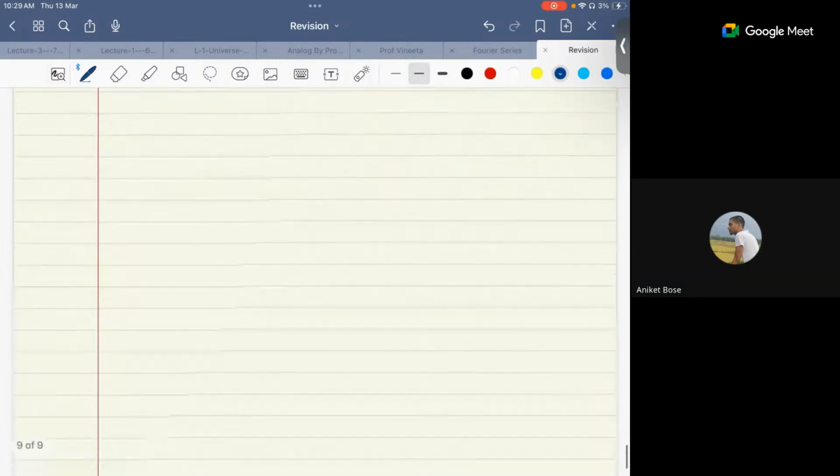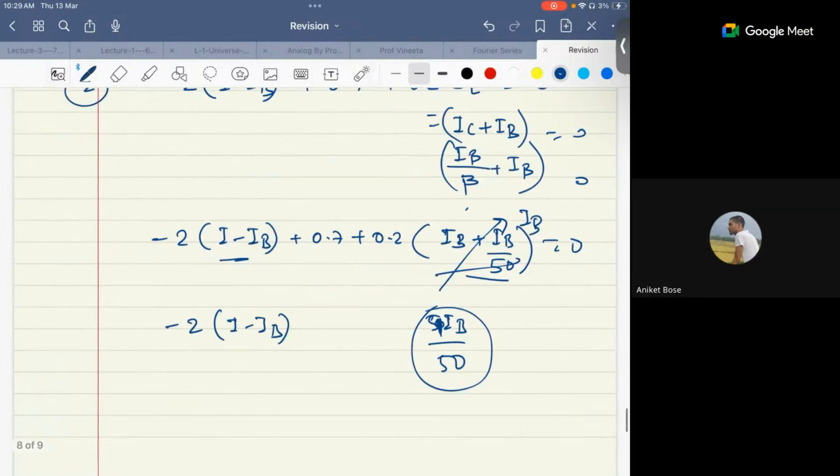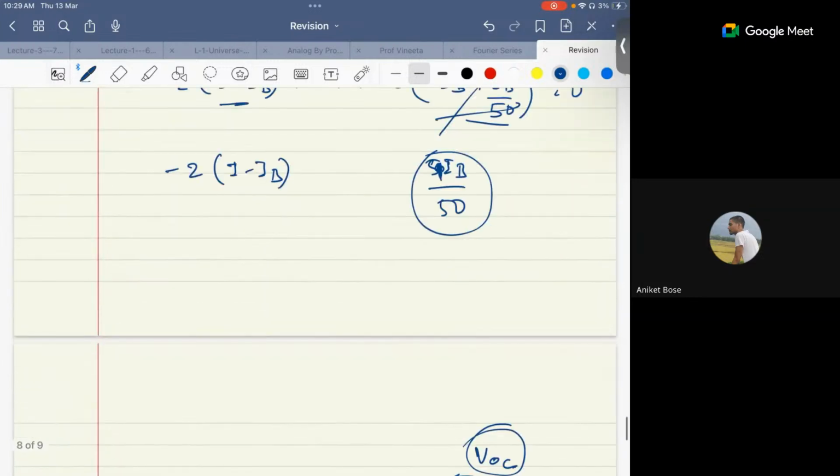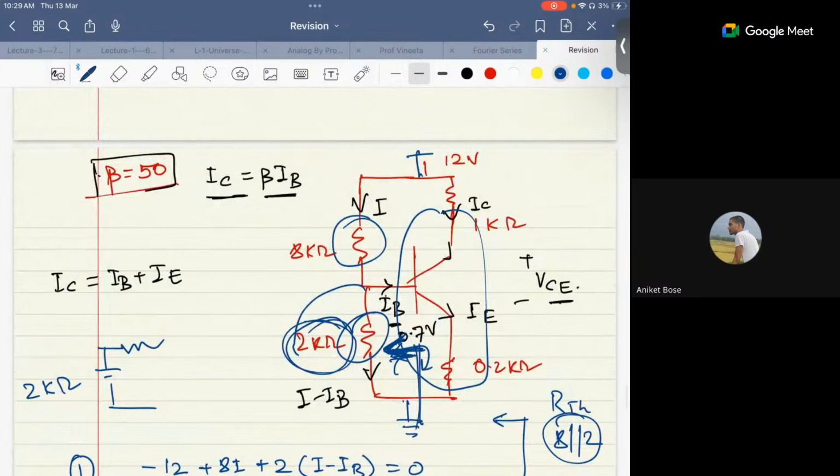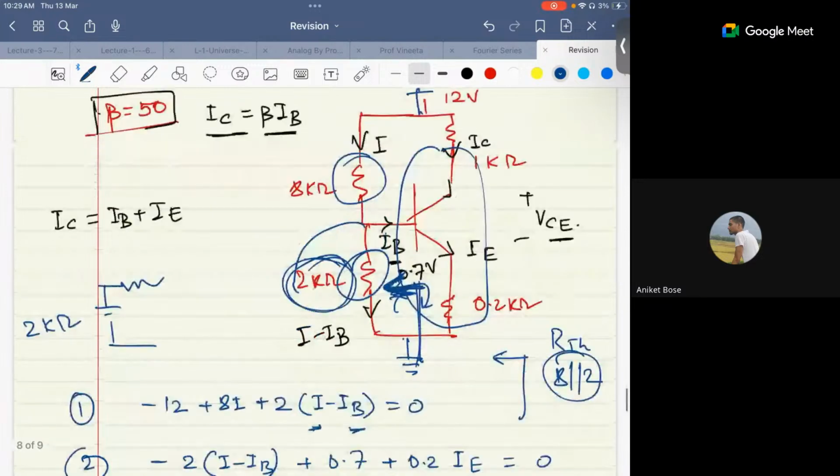See, you are calculating, for example, with this BJT. And one more thing, I guess I mistakenly said it. Even if you have IB, whenever you calculate the voltage, you just assume it as open, and then you calculate the Thevenin voltage V Thevenin. Even though there is a current, we don't worry about that. You can calculate VTH for those cases also, no problem.